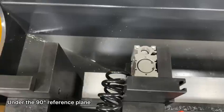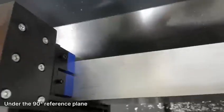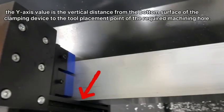Under the 90 reference plane, the x-axis coordinate value refers to the horizontal vector distance from the reference plane of the positioning plate to the tool landing point of the target machining hole. Under the 90 reference plane, the y-axis value is the vertical distance from the bottom surface of the clamping device to the tool placement point of the required machining hole.